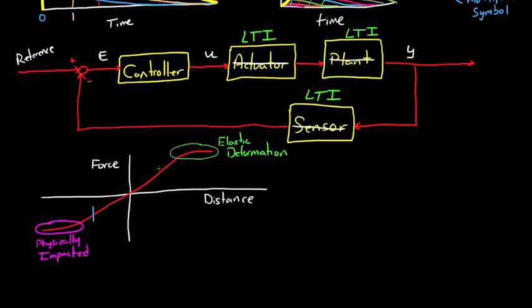Somewhere in between, in what could be considered the operating region of the spring, there will be a nice, nearly linear relationship between force and distance. If you were selecting a spring for your project, you might specify the region of linearity, that is the range of forces that the spring will likely see, and how linear that region needs to be.